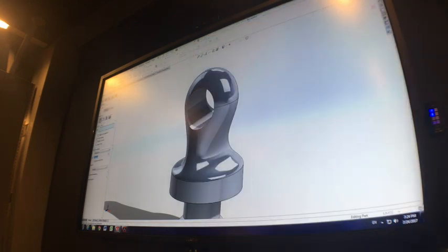Fillet, I select the face, and nothing happens. Now, if you ever see this with a fillet and you've got full preview on, the next thing you need to check is the dimension you've got in there. So this has a 10mm radius, which is way too big because the hole is only 11mm in diameter. My suggestion, whenever you've got fillets, you can't see them working, go to a small size and then work them up until they no longer work. So the fillet on this part is going to be 1mm. You can see there the preview works.